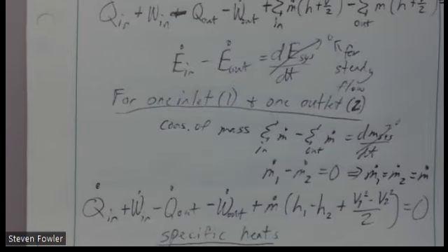And at least if you've written it down in your assumptions and made it clear, hey, I'm simplifying this because I'm assuming kinetic energy is negligible, or V1 equals V2 is a simple way to write that, then if it's not actually correct, I know you didn't just copy some equation without knowing how it worked. You made a conscious choice to use that version of the equation.